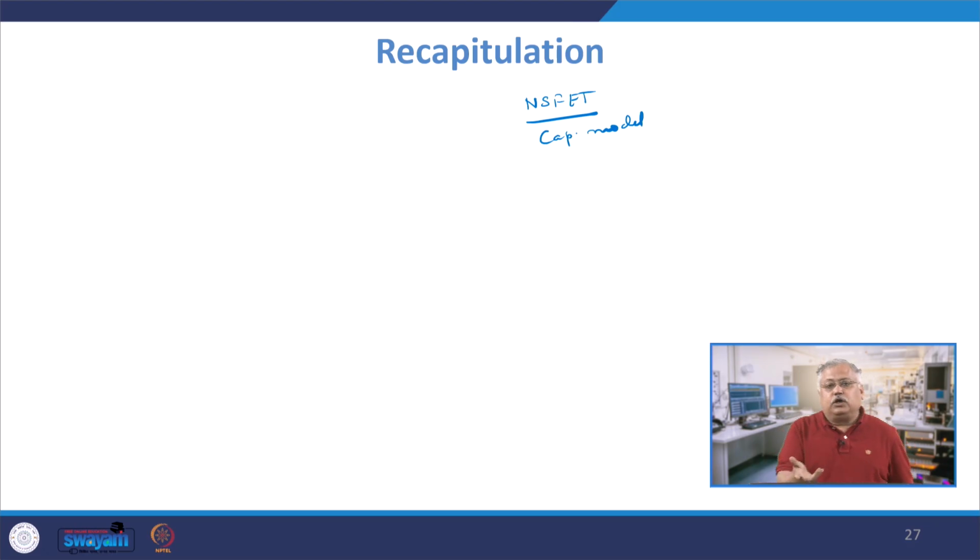These capacitive models are subdivided into various types which are physically validated. They are also compared with the analytical model, and a good match is found between the two. And finally, we looked into how the overall capacitance varies with the number of sheets and the structural parameters available to us. So this gives me a holistic idea about the various elements in a nanosheet FET.